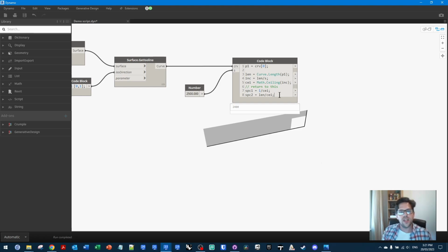We actually want to move these by half of a spacing in the domain, which we have here in spacing 1, so 0.2. So we actually want to move these 0.1 forward in sequence, so that we're between each point of the domains of the panels. It'll make a lot more sense once you can see this visually represented, so I'll just work my way through this step. But we're going to create a sequence, and I'm going to say the sequence is equal to half of the spacing in the domain aspect.